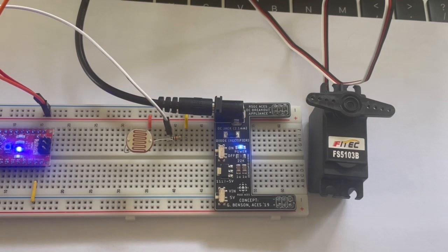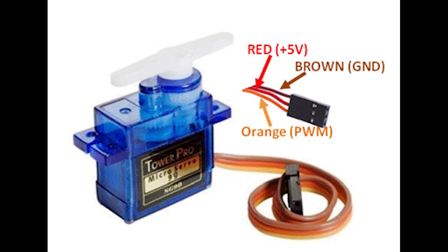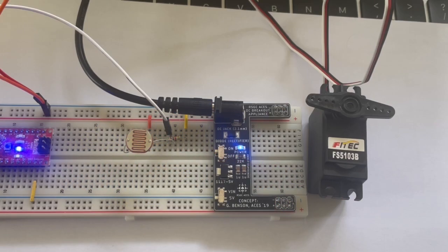The three primary components of the circuit are a continuous servo motor, an LDR, and the Arduino Nano. The servo has 3 pins, the power, ground, and signal pin. The signal pin receives commands from the Arduino through the write function in the servo library. The parameter used in the write function is the angle at which you want the motor to move to.